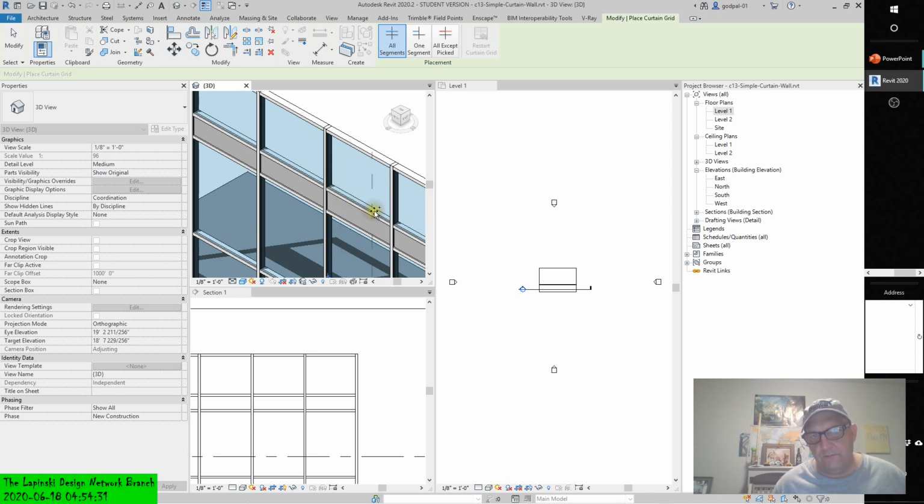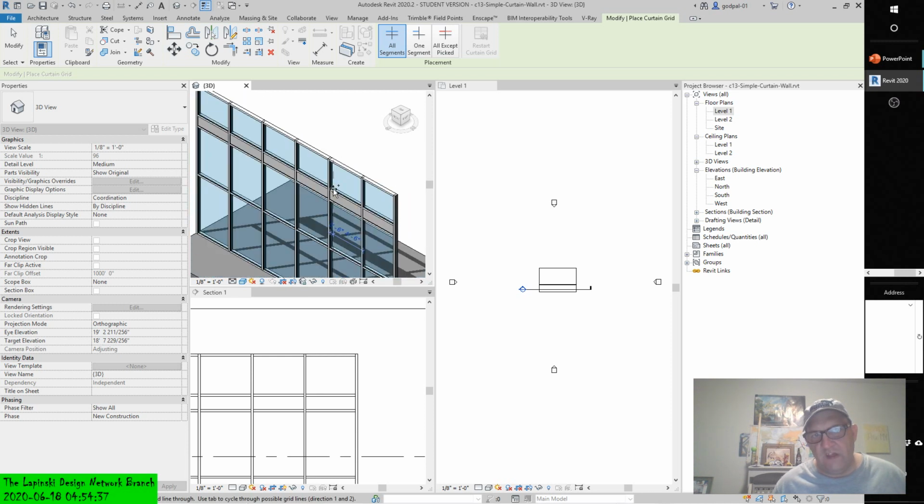Notice there are guides that divide up the panel. Right center panel, midpoint. And snap to the midpoint of the panel. The second step is tricky. You do not continue creating another division in the short panel above the center panel. Instead, press the Escape key or click the Modify tool.